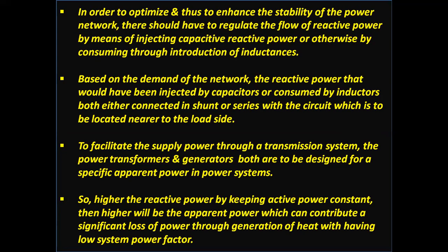In order to optimize and enhance the stability of the power network, the flow of reactive power should be regulated by injecting capacitive reactive power, or otherwise by consuming it through the introduction of inductances.